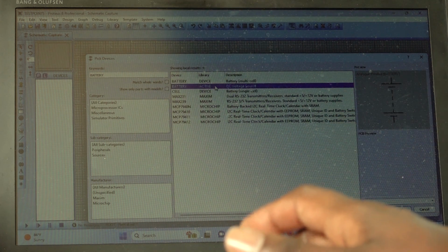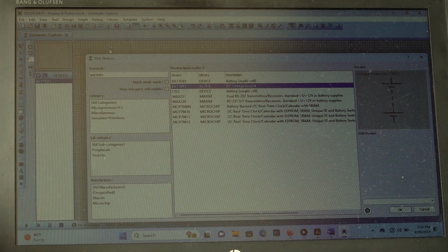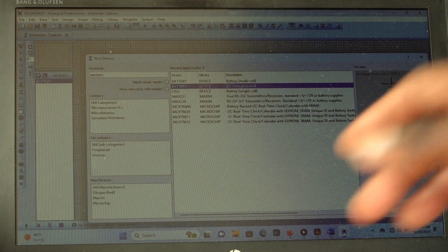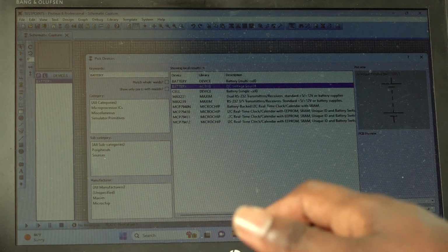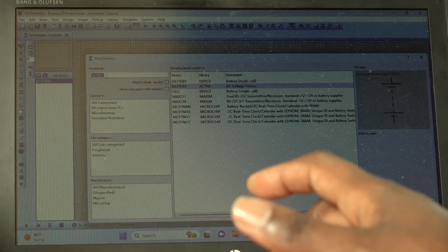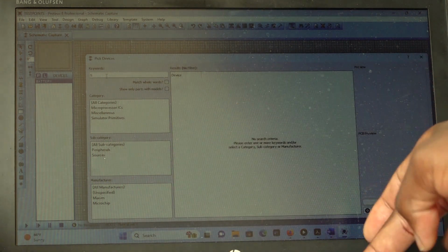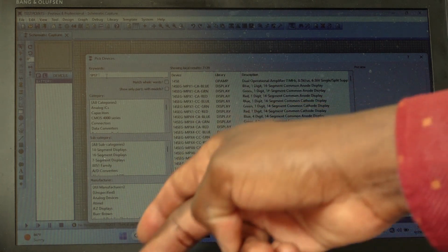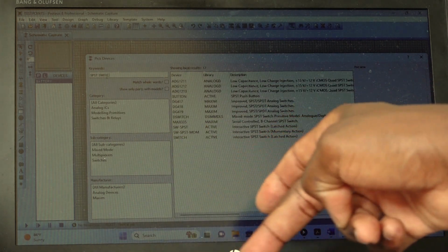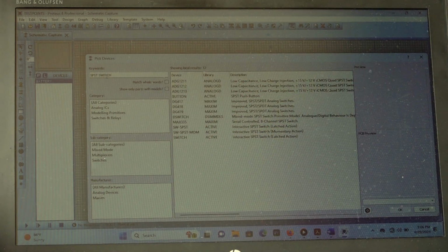So then let us choose these components. So we place in what? Object selector window. The next component, resistor 1. No, the switch. The switch, I told you that is single pole, single throw switch. I taught you the shortcut of searching the components quickly. Are we together? Yes.